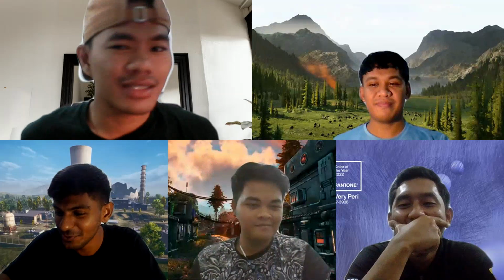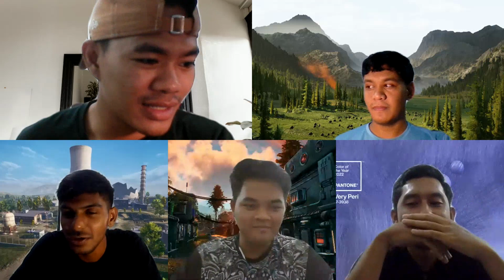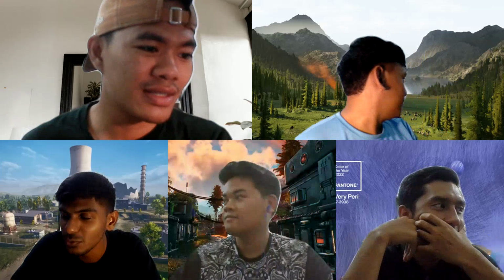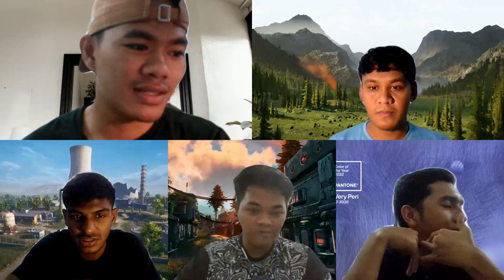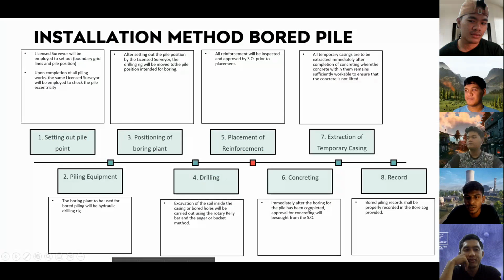So I will talk about the installation method for bored pile. So firstly, the point is setting out. For setting out, we will hire a licensed surveyor to do the setting out. The surveyor will set out the point and the original ground level. Then the surveyor will give the as-built drawing to know the accuracy of the pile position.